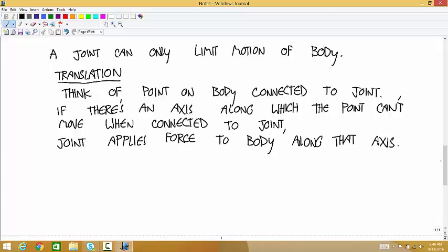But in something like this, there are other cases where it's not too uncommon a thing, because it's a normal force that prevents, like this is also a joint, this pin touching the table. And if you ignore friction, what's the axis along which translation is prevented? It just can't sink into the table. It can slide side to side. So we'll have a lot of times where the force produced by the joint is perpendicular to a surface, yeah. But it can be the other way. It can be different. Yes, right.